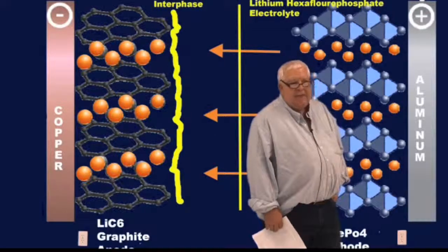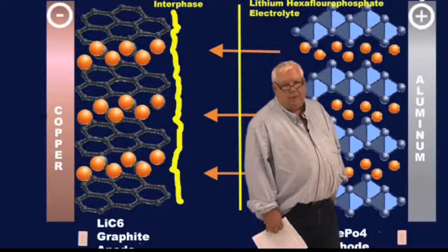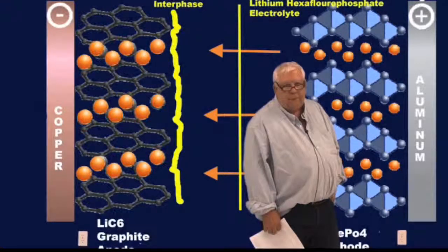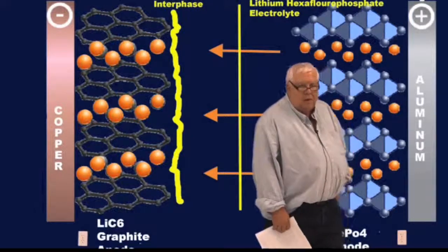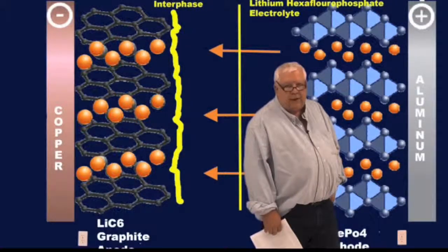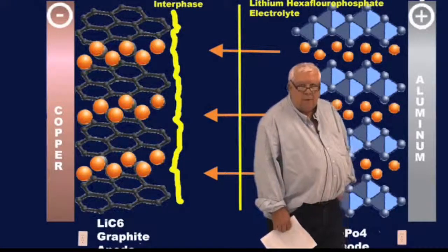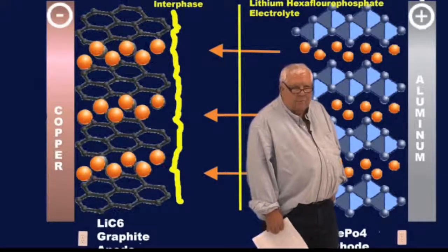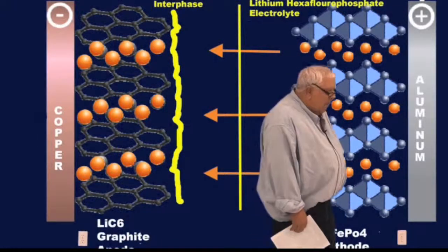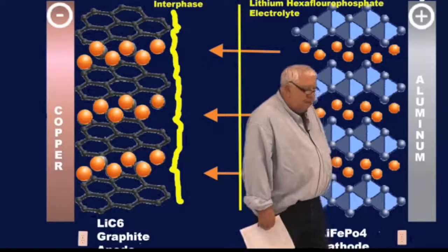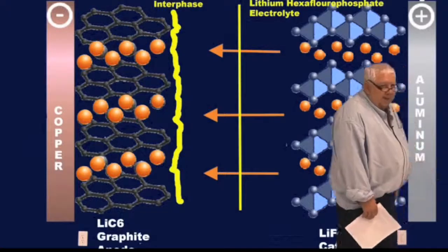We can't mix lithium with carbon and paste it on the copper and do any good with it. It just doesn't work. And so we can combine lithium readily with ferric phosphate or iron phosphate. So they combine lithium, the metal, with iron phosphate and a binder and some carbon, and they tumble all that very well and glue it to our aluminum current collector, and we have a cathode.